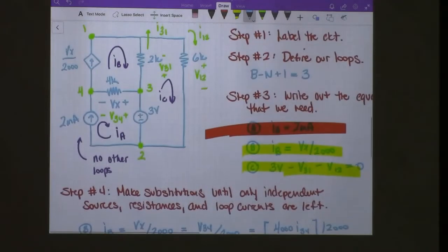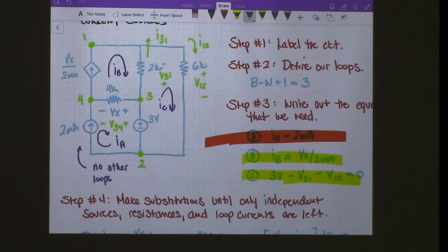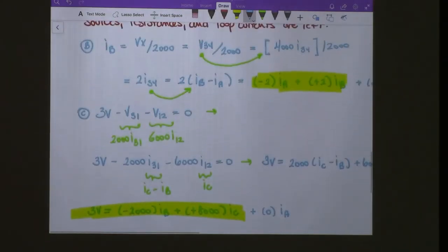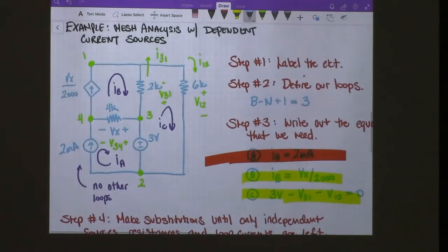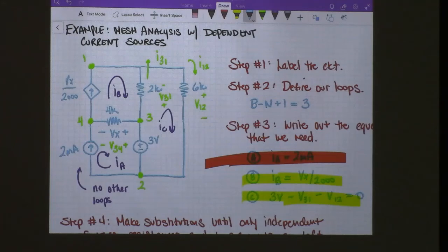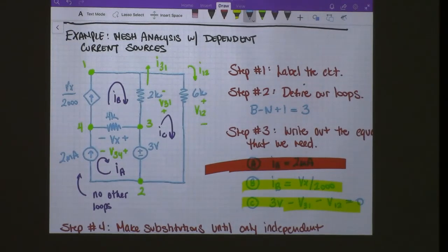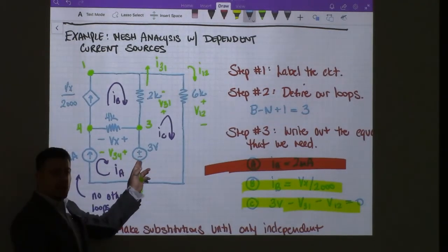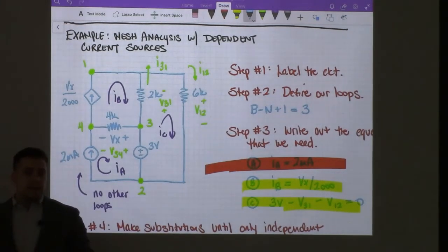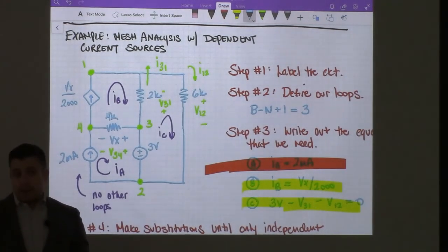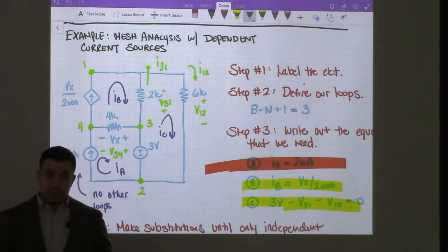So it all comes down to the math, because when you look at loop C, the only place where IA would come into play would be here, right? That's the overlap between IC and IA. The thing about it is we don't use Ohm's law at that branch because it's a voltage source.